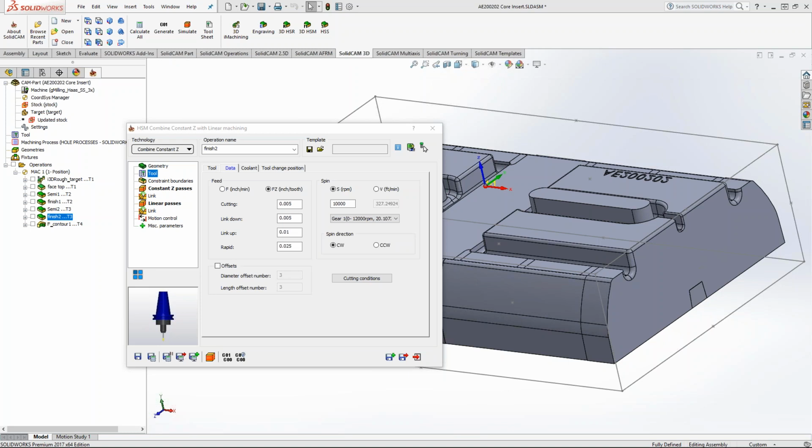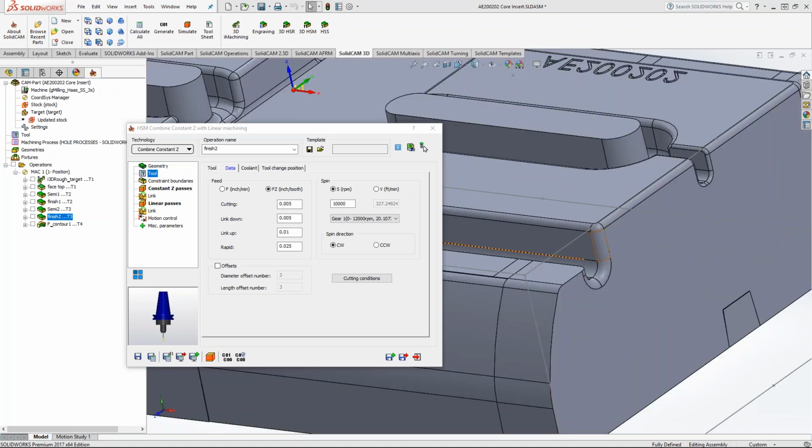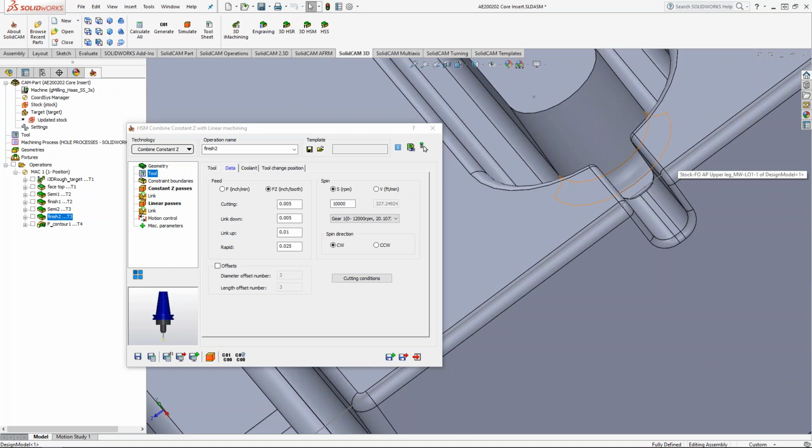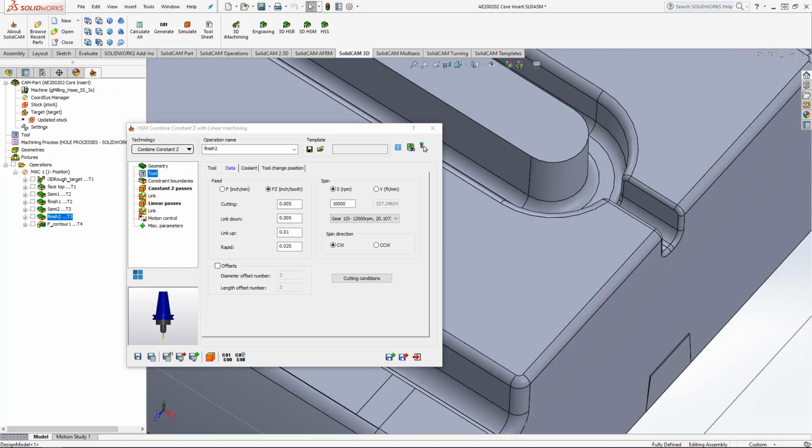Again, HSM is going to allow you to do the whole thing and work off the model. So it's doing the gouge checking on the whole model. Whereas with HSS, you've got to be careful and make sure you pick your gouge check surfaces. But for doing detail work, smaller areas, I prefer to use HSS because I can define which area I want to work on just by picking the surface.